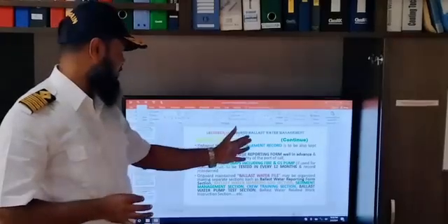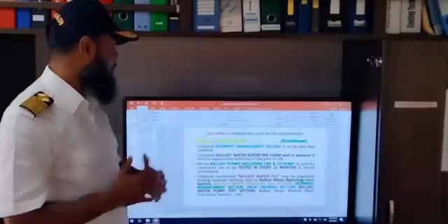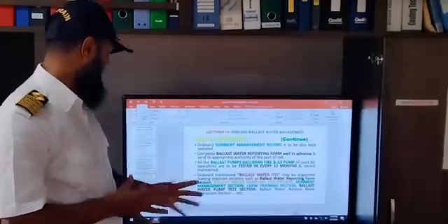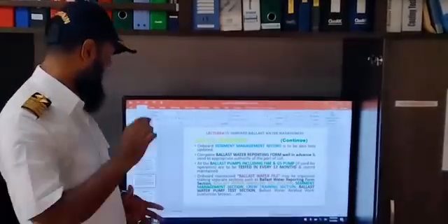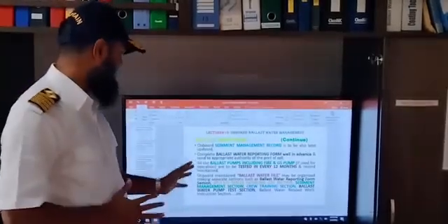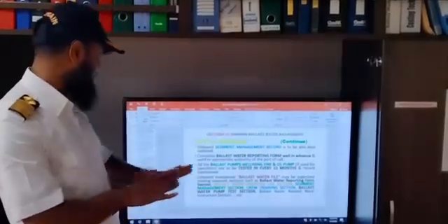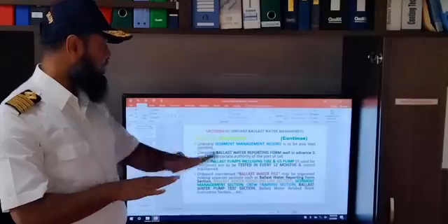Sediment management records must be kept up to date. And complete the ballast water reporting form well in advance and send it to the appropriate authority of the port of call. Ballast pumps, including fire and GS pump, if used, must be tested every 12 months and records maintained. The onboard ballast water file may be organized by making separate sections like ballast water reporting form section, ballast water handling log section, sediment management section, crew training section, ballast water pump test section, and so on.